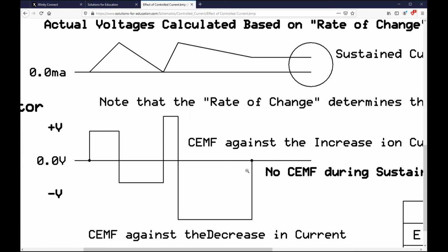Oh, I was thinking about the field windings on motors, which carry a lot of current, but that's okay because it's just circulating in there. And then if some student in the lab, for example, pulls the wire from the field winding, then the magnetic field collapses, and guess what? It will generate absolutely any voltage necessary to keep that current going, which can be thousands of volts. You can draw a huge arc when you pull the field.